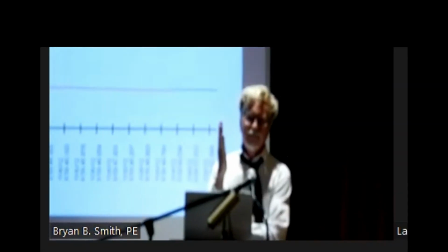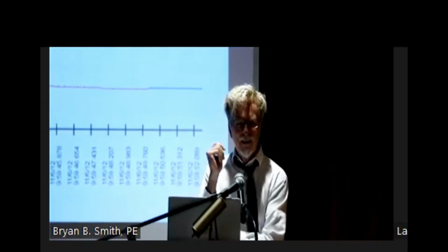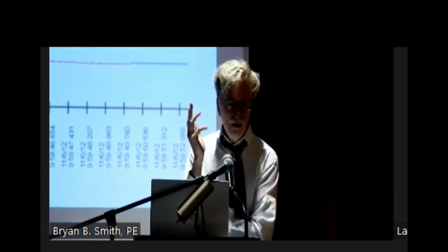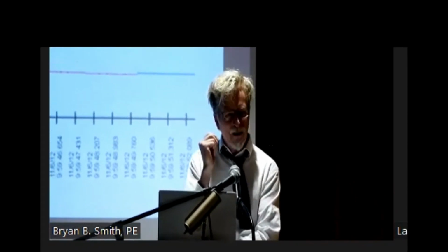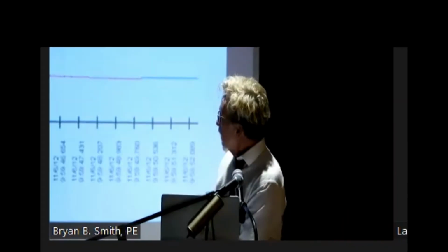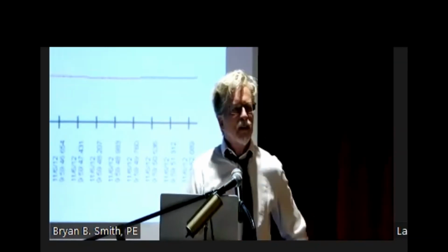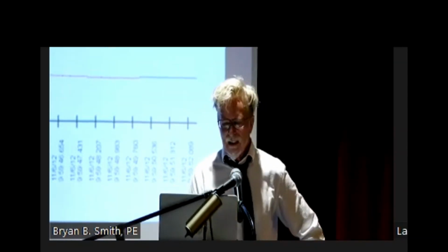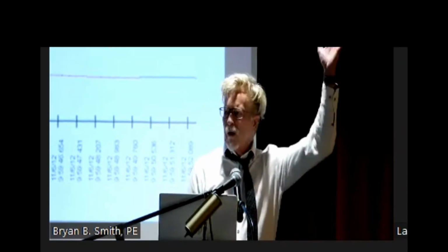So step one, when I get involved in a project: do you have a surge model? Can you send me the model? Can I run it on my computer? Before I go to start that up, I want to know what's going on within the system so you don't have a situation like this. So that's the fear factor in engineering 101.